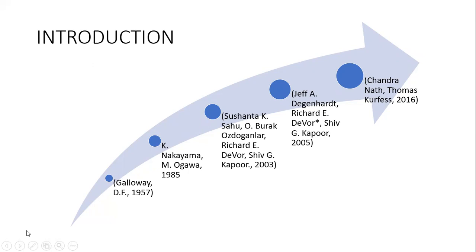Galloway demonstrates that very small variation in drill bit geometry can have a very significant effect on drill bit performance. Makoto Ogawa made the splitting nick on the cutting side of the lips of the twist drill to break up the chip that came out of the drilling process. Although the research resulted in lower drilling torque and better surface finish, the problem of chip length has not been solved.